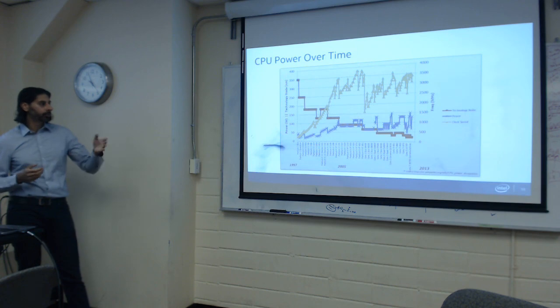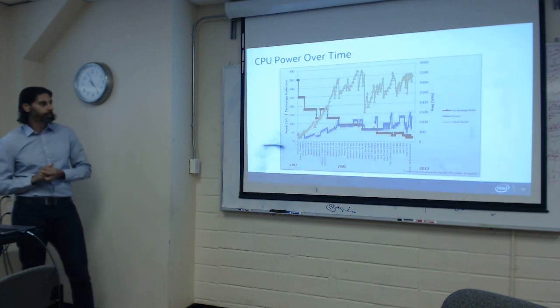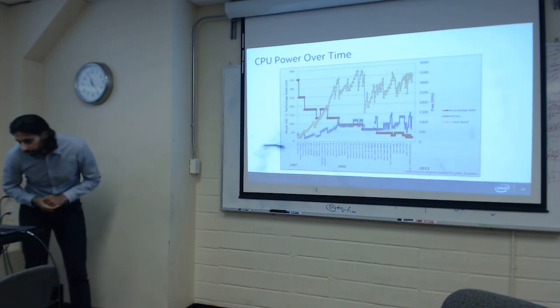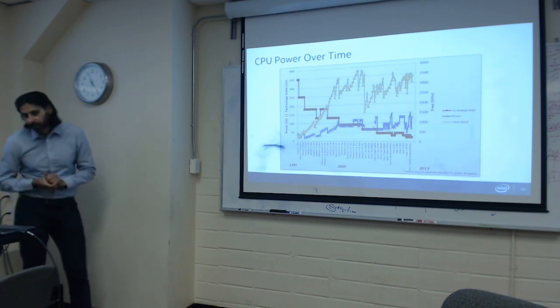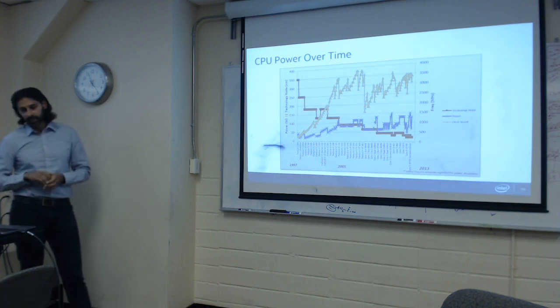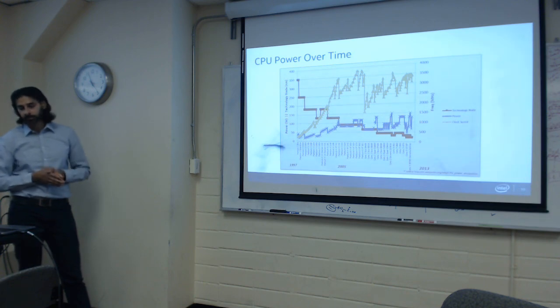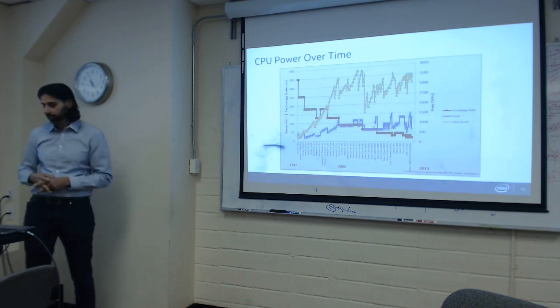And the key insight there is, if you look at the purple line, which is the power dissipation of these CPUs, they steadily went up as clock frequencies went up, and then they kind of hit somewhat of a wall at about 100, 150 watts range, and they kind of stabilized. So that's the key thing that changed the way CPUs were architected to not just focus on pure clock frequency and be limited by the amount of power that you can actually provide into the compute.